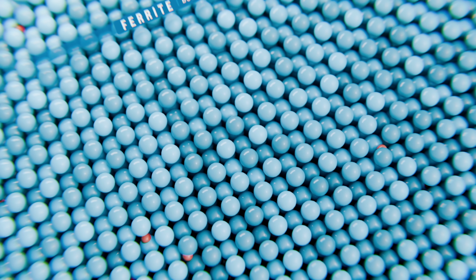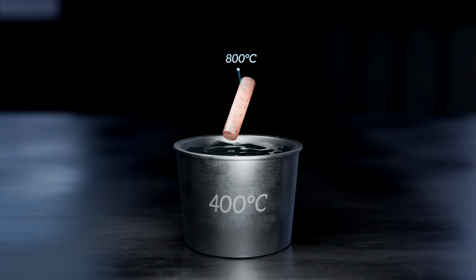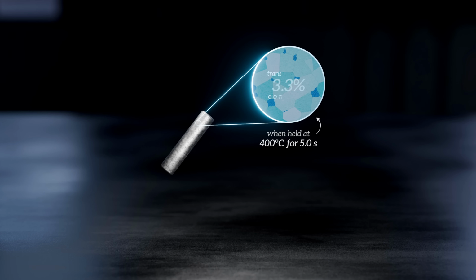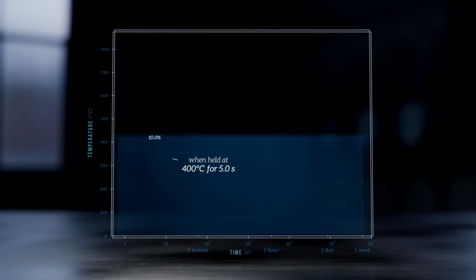The time it takes for a phase transformation to occur can be determined through testing. A small sample is heated until it's fully austenite, then rapidly cooled to a target temperature and held there for a set amount of time. After this hold, the sample is rapidly cooled to room temperature to interrupt the transformation, and the microstructure can be examined to get an idea of how much of the austenite has turned into ferrite and cementite. By repeating this test for different temperatures and holding times, you can start to map out the relationship between time, temperature, and the phases that form in a given steel.